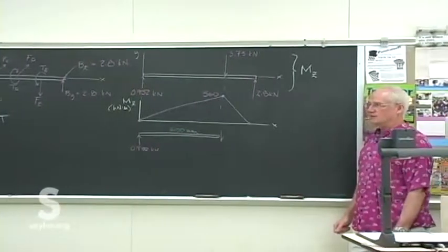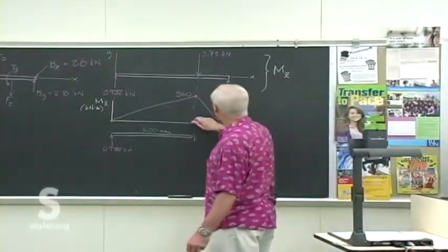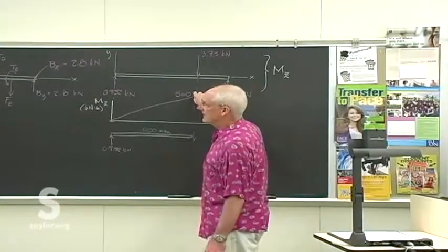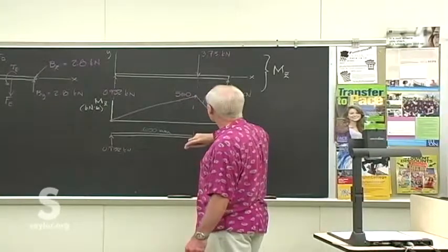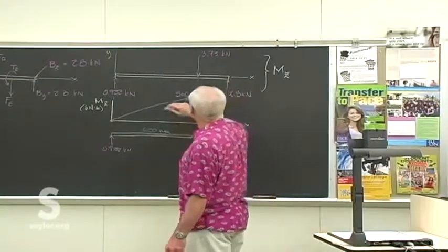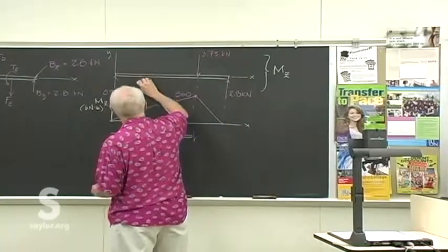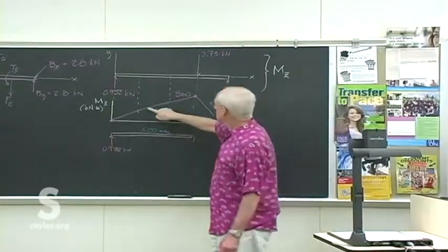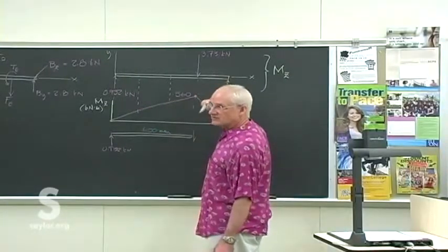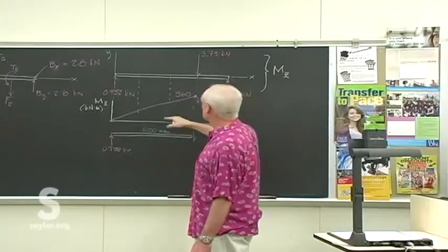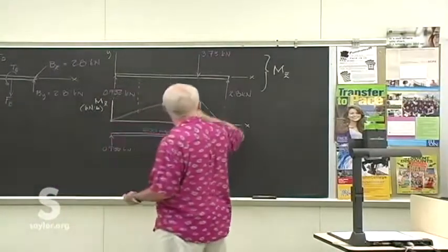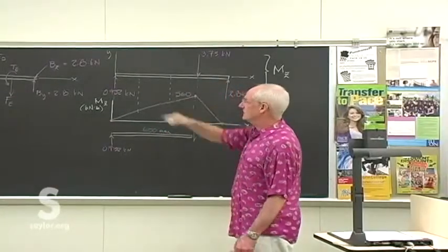for this view. And we see obviously in this direction the worst spot is on that gear E. But it allows us to also find the values at gears C and D. We can then take these values, add them to the values we're going to find at C and D in the other direction, and that will tell us which one of those points along the beam is the worst case. So right now it looks like gear E, but we have to check the other two directions.